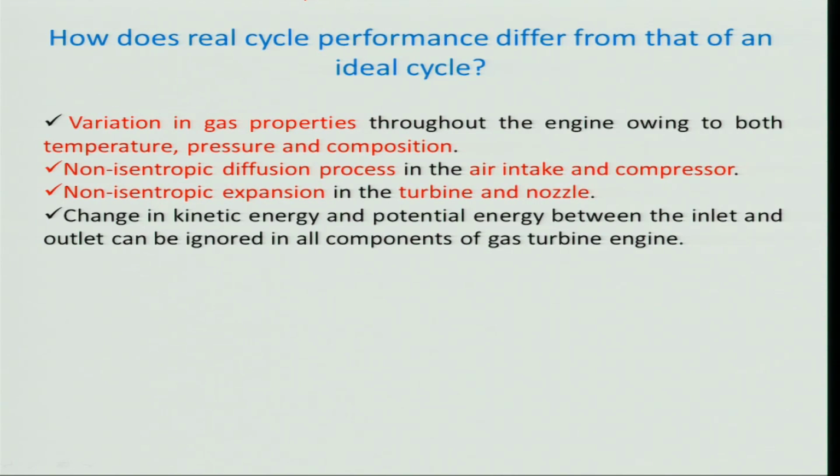and of course, potential energy is not very important, particularly for the case of a gas turbine engine, because all will be at a similar level. But when you use centrifugal compression and centrifugal turbine, we need to worry about it, but those contributions will be very small. In the case of a steam turbine and others, you might know potential energy plays a small role, but here in this case we need not worry about it.